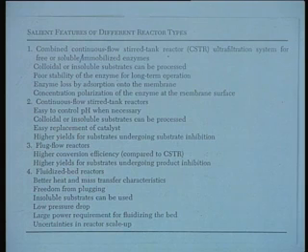In the case of a plug flow reactor, you have a recycle system, so that I have an external loop in which the pH monitoring and control is exercised, or otherwise, in an ideal plug flow behavior, the pH control is difficult. But the CSTR can provide you an ideal tool, and in many cases of immobilized enzyme reactions, pH control is a requisite. Then of course, in the case of CSTR, even colloidal or insoluble substrates can be processed, which is not feasible in the case of plug flow behavior.